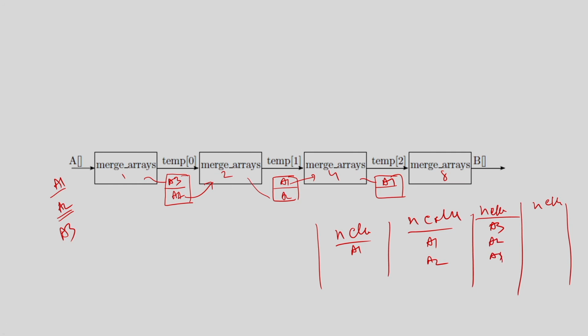Next clock, assume. So, now what is going to happen? This block will take A1 and do the merge by 8 and it will give you the actual output, right. So, it will do processing of A1. This other block will now take data from A2, because this is already processed, and do merge by 4.